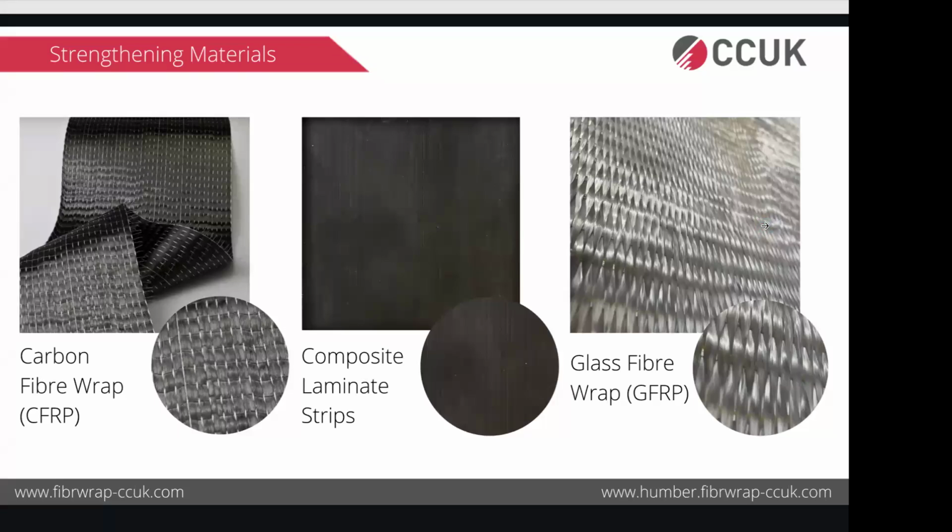So there is also GFRP material, which is glass fiber reinforced polymers. The similar sort of theory works here as well. So in the fibers, you have glass fiber here and the same epoxy. Whenever I say GFRP, people usually get confused between GFRP and GRP. The difference between those two materials is that GFRP is a structural material because it has a continuous strand of glass fiber which can transfer the stresses, as compared to chopped strands of glass fiber in an epoxy matrix, which is used to make formwork or liner. So that's not a structural material, whereas this is.